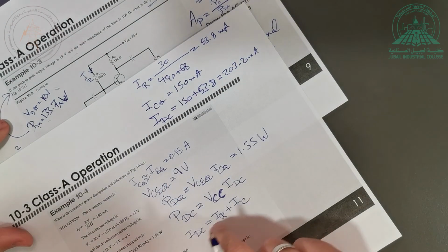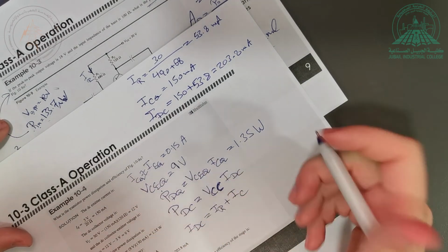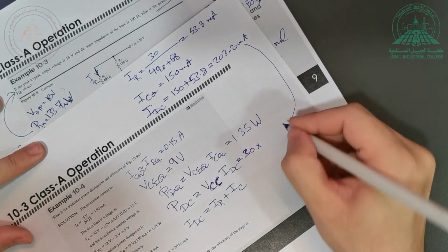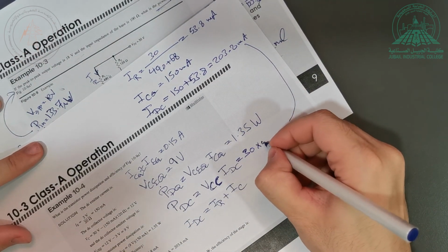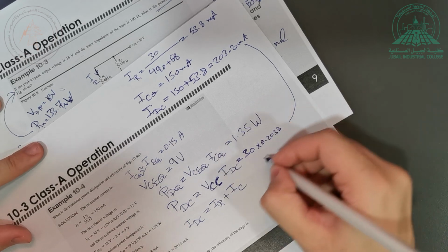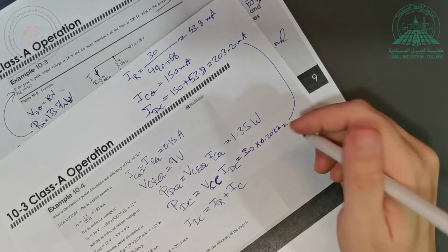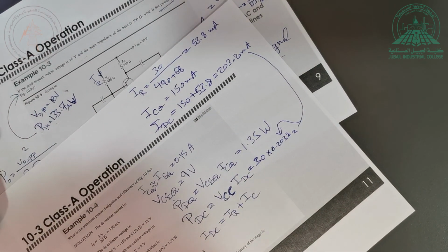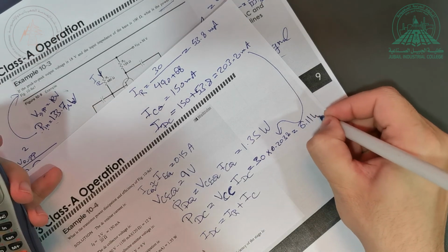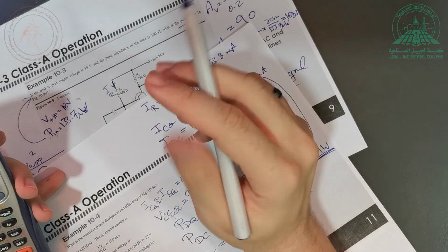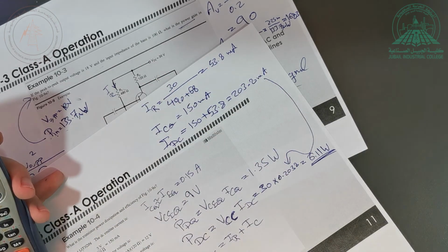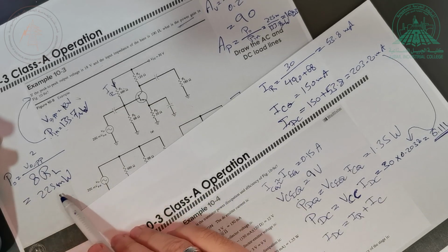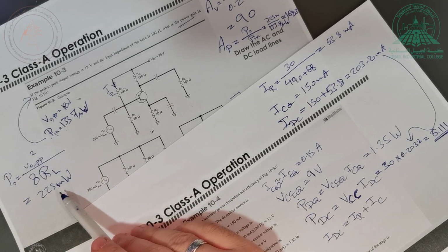When I have this current, now I multiply it here. So it's equal to 30 volt times 0.2038, which gives us how much? It's in here already. 6.11 watt. See, a relatively huge amount of power is being supplied by the DC. And how much reaches the output? See how much the output is? Less than a quarter watt.